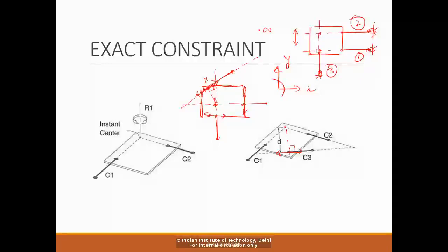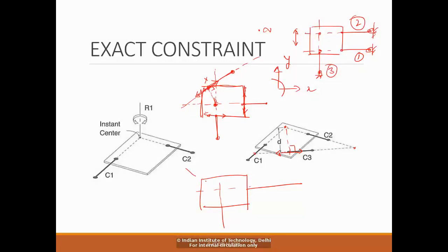So one object cannot have more than one center of rotation at a given time, right? Same thing is happening here also. You have one here, one here, right? Now, what happens if I have lines like this, so intersecting, right? And then I say, okay, I have another one, but passing through this point, whether this will do anything. It will still have this rotation, and in this case, it's an over constraint design that we have to understand.